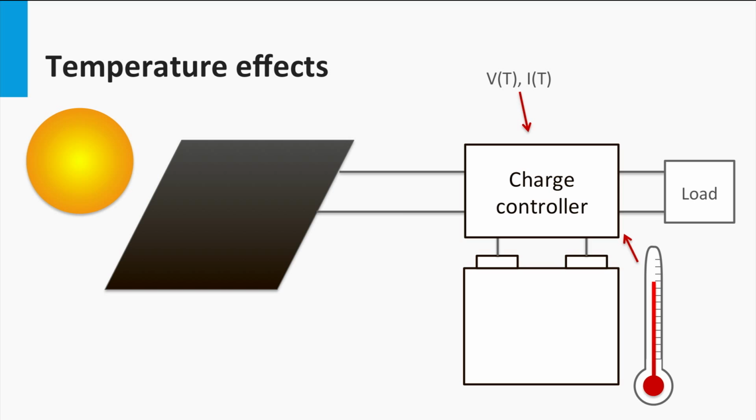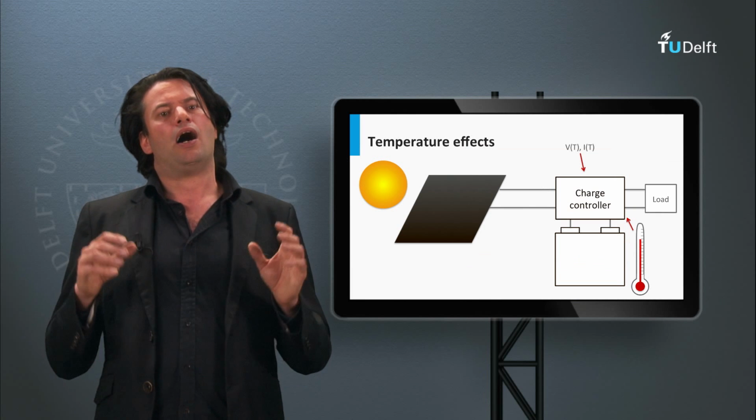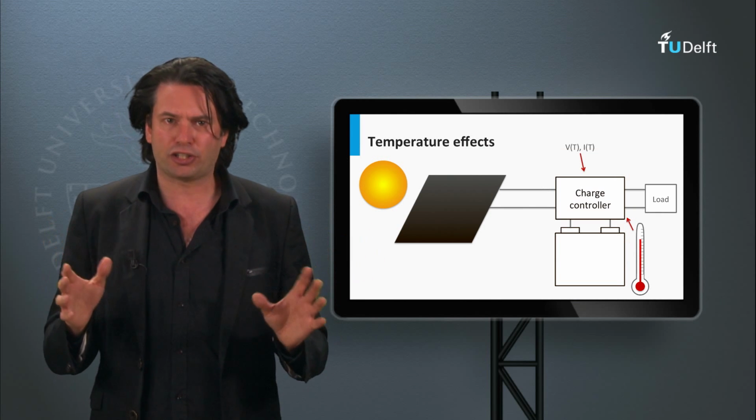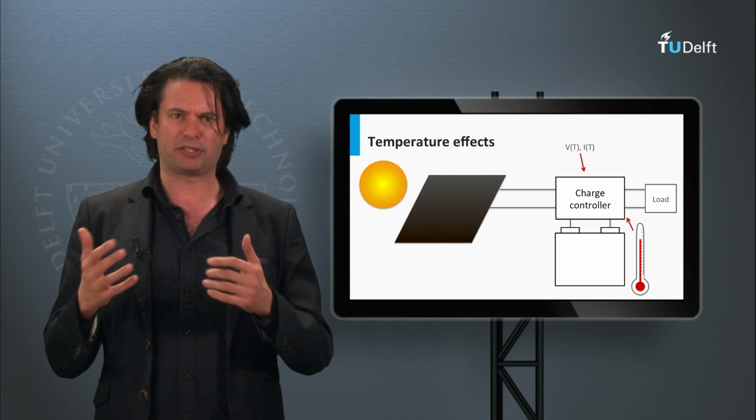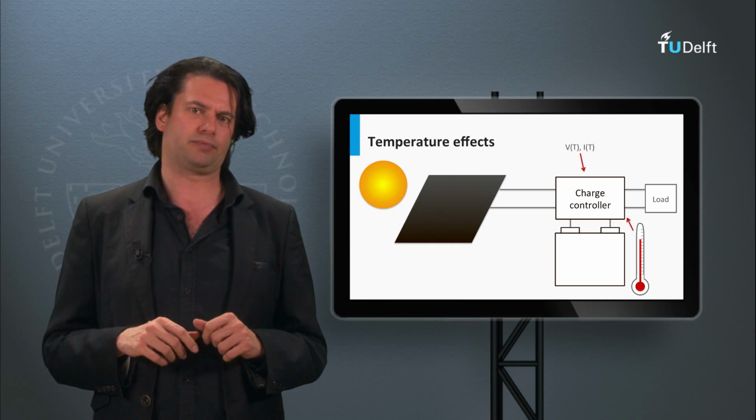In extreme cases, if the battery is heavily loaded, sustained high currents might heat up the battery, and the charge controller would expect a different battery operating temperature than the actual value. However, high-end charge controllers are being designed to also take into account the temperature effects due to high currents.